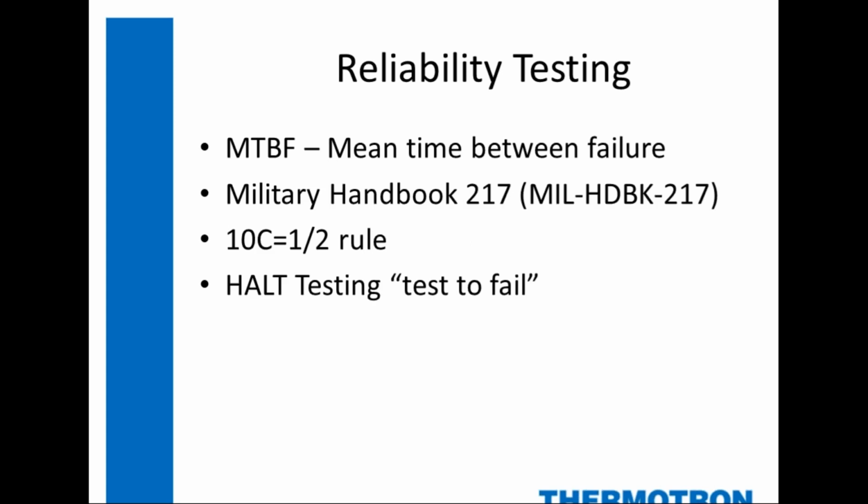So one of the other types we'll see is trying to predict the reliability of a certain product. Product reliability is quantified with something called mean time between failure, or MTBF. So reliability engineers will use resources like the Mil Handbook 217. There's a lot of software out there that you can plug in different parameters and it'll give you a mean time between failure. And there's just a ton of formulas and a lot of pretty complex math that gets into reliability engineering and what stresses will do to the end product.